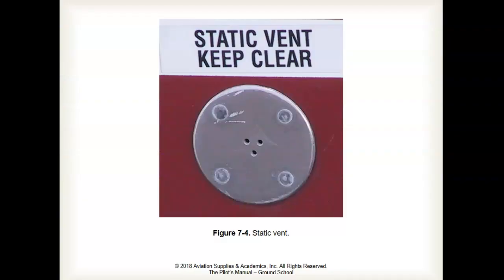Because the static port provides information to all 3 pitot-static instruments, it's very important to check the static ports before every flight during your pre-flight inspection to make sure that the static ports are not blocked.